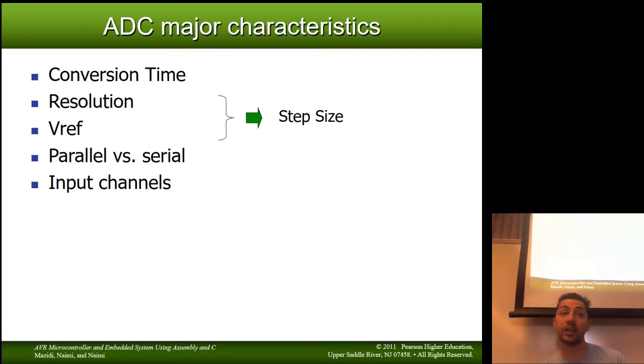Some were meant to go really fast, software-defined radios these days, which have bandwidths of 100 megahertz for the very nice ones that you can get in a research setting. You've got to be able to sample 100 million times per second. All of that feeds into conversion time. How long does it take for you to get a reading?